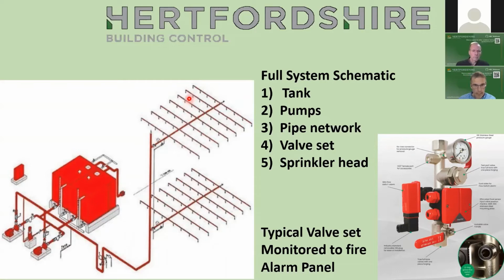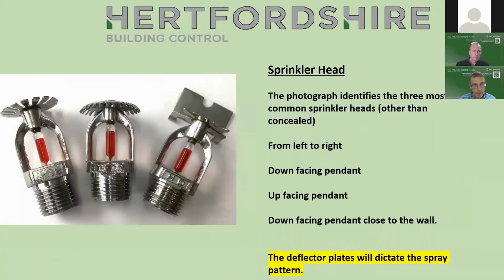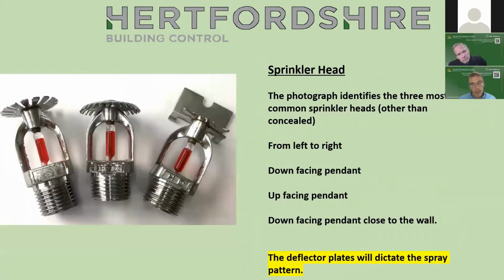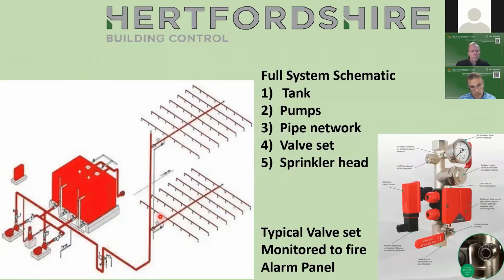The second port of call is that all of these sprinkler heads, if we go back, have got different, or can have different size holes in them, and they're called K factors. So the bigger the K factor, if you've got a K factor sprinkler head that's 120, it's got a bigger hole than it would have if it's a 40, which is going to have a smaller hole. So the idea is that these sprinklers here will have small holes, which will be small K factors, and these sprinklers here, which are going to be subject to less pressure, have got bigger holes, and that balances it all out. Otherwise, you'd get the design pressure out of this sprinkler, and you'd get probably 3 times as much out of that one. So that's a bit of knowledge on how these things are balanced up.